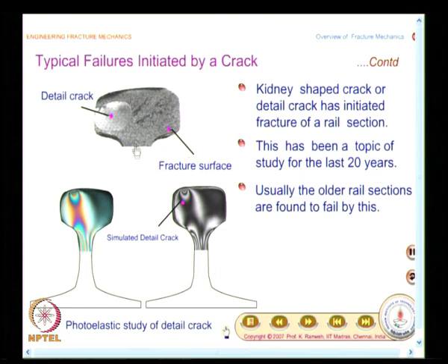And the important aspect here is, the crack has appeared below the surface. Here again you see the crack surface and fracture surface. So, there is a growth phase followed by fracture. This is what is emphasized here.